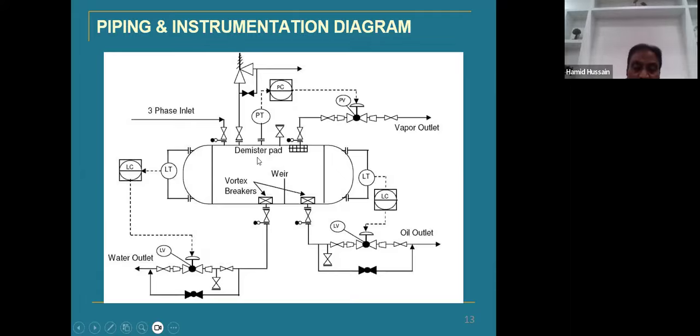This vessel may develop certain pressure. That pressure has to be monitored, and that monitoring instrument is the pressure transmitter. The pressure transmitter has a pressure control which is inside the PLC or DCS, and this is a DCS symbology, while this is a field instrument, this is a field instrument. I'll show you the international standard ISA S5.1, which shows all these guidelines, what these symbols are and how they should be shown. This is a safety valve.